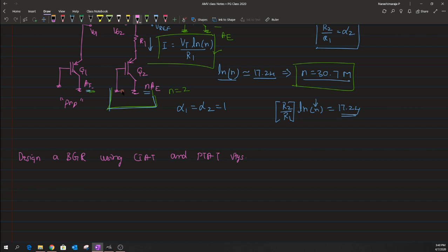Okay. So the parameter values are VDD, which is equal to 3.3 volt, and a DC bias current of 5 microamperes, and a factor of n that is equal to 2, and this is meant for PTAT generation.